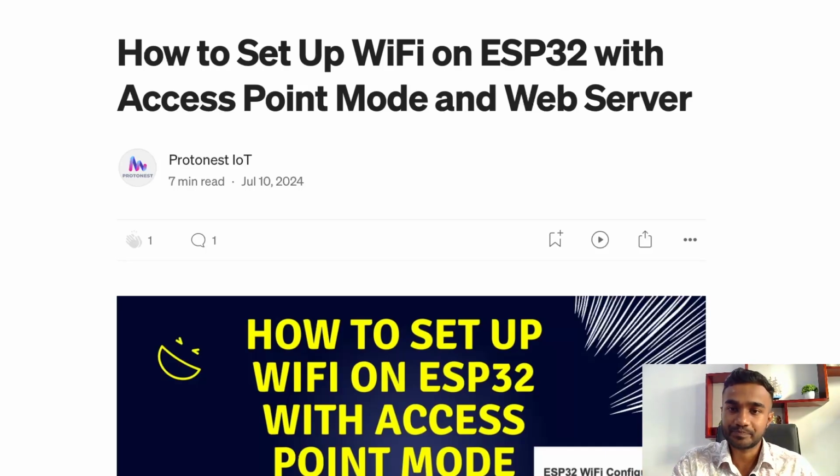Another method is you can use smart config, in which you will be able to connect with your ESP32 through a mobile app, and through smart config you can provision the ESP32 with Wi-Fi. So that is one way you can use smart config plugins on your customized web or mobile application. Another method is you can use BLE. There you are able to connect with BLE and just add the credentials through a mobile or a web application. You can just use any according to your requirement, so you will be able to update the credentials.